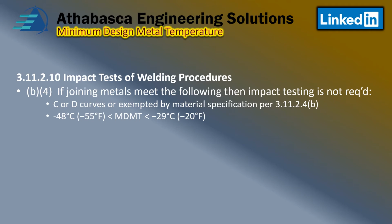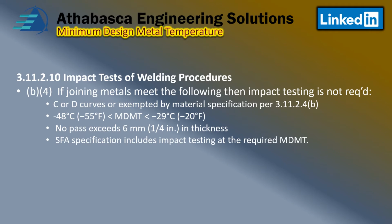You have a temperature between minus 48 and minus 29, and no pass exceeds a quarter of an inch in thickness, and the SA specification includes impact testing at the required MDMT.